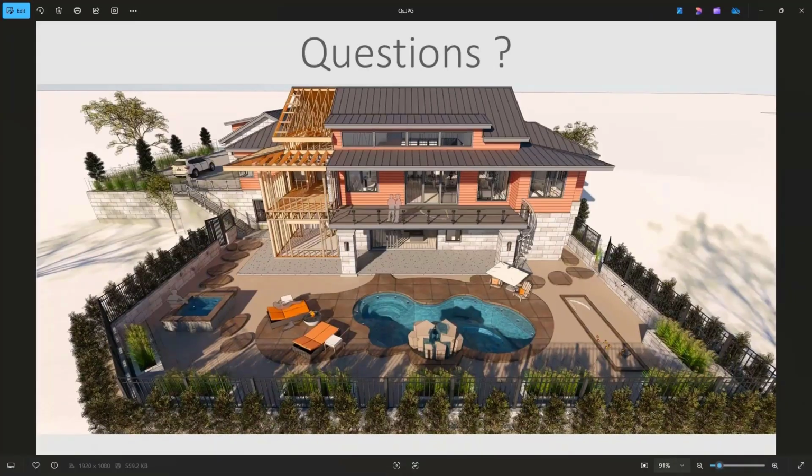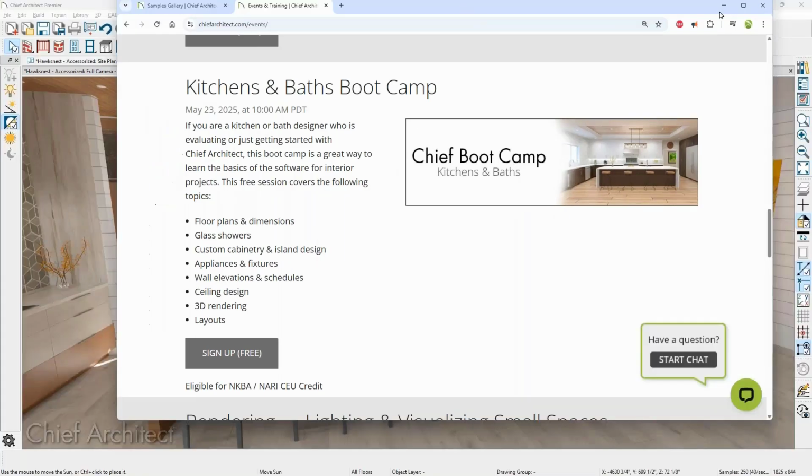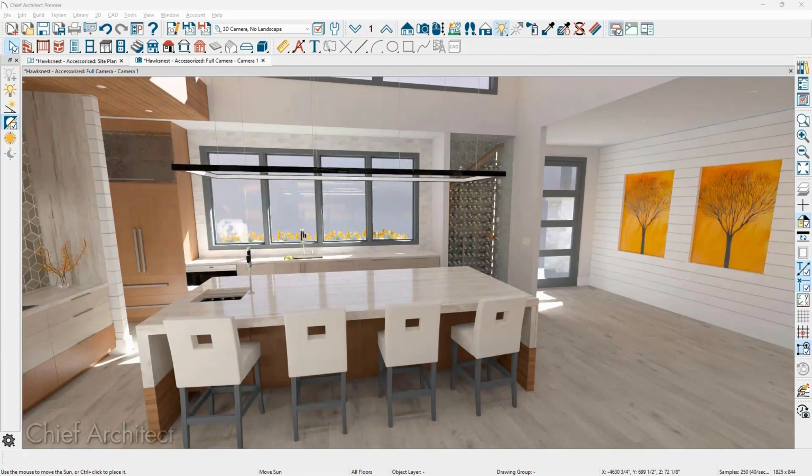Oh yeah, go ahead. So one thing that you could do is create a normal walkthrough path and put the start and end keyframes close to each other, and then you could set the sun angle on the start and the end at different times, like where you want to do your sun study, and you can actually look in the walkthrough preview panel and scrub through that, and it'll take into account your latitude and longitude and the times that you've set in, but it won't take as long as actually recording the whole walkthrough. Okay, cool. Well, thank you very much.